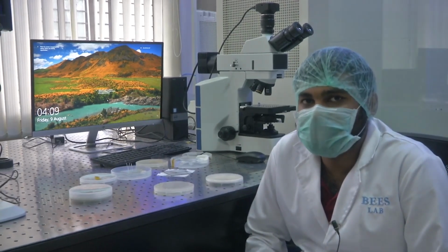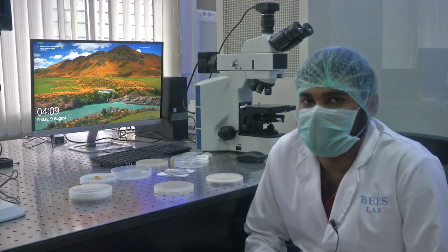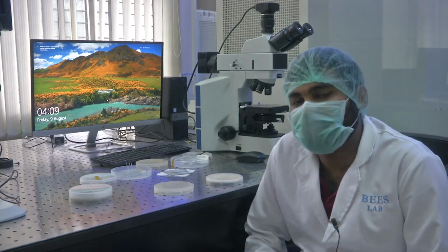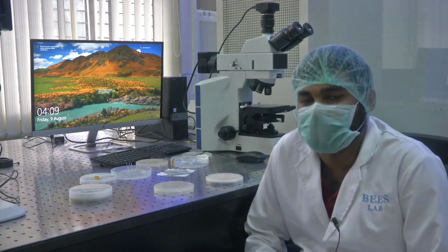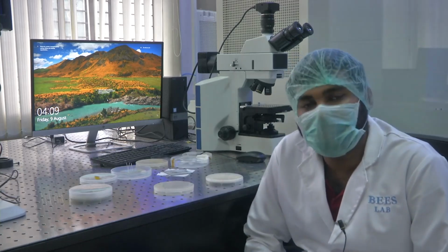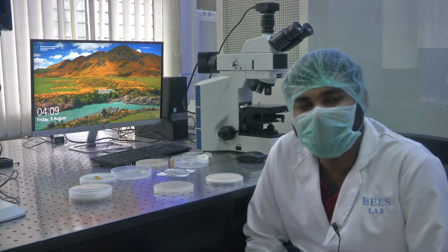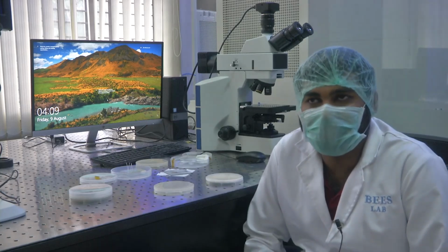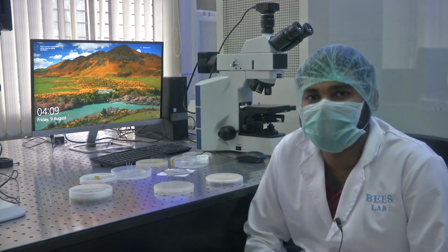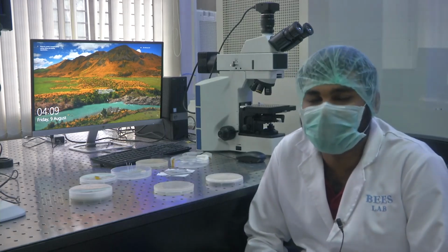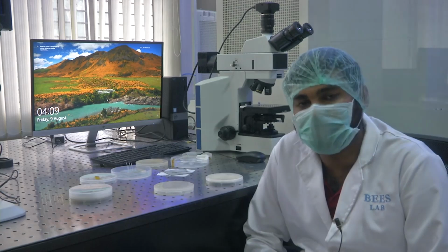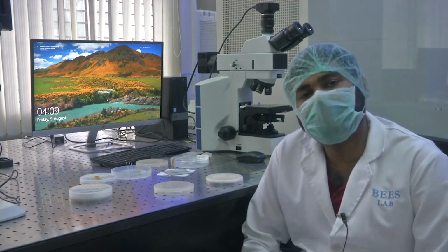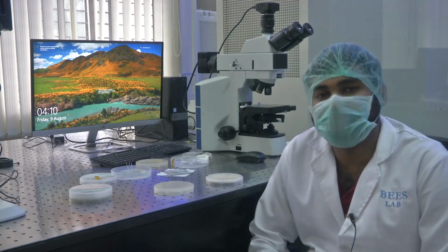Now, we will see a few devices that are fabricated on silicon wafers. The majority of devices would be on silicon wafer, and a few microfluidic devices are mainly done on glass wafers, generally. As I told you, before you make any device, you have to clean the wafer, as the professor would have told you, then you deposit a specific material, especially sensing materials like for electrical sensors. Mostly we use some metal, like platinum, gold, or aluminum. You might use nickel or nichrome for a micro heater. So, many different types of metals may be deposited on a silicon wafer.